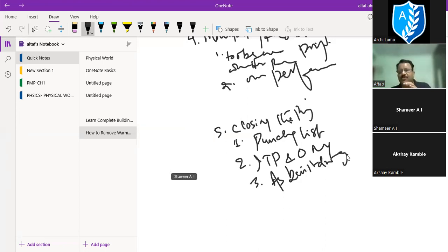What is an as-built drawing? Once the project is over, in the closing phase, from start-up to closing phase, maybe there are some changes in the project. Some part, definitely, there will be changes. Lots of changes are there in projects. Those changes are certified by the client or client engineer at those times, and they are checked along with the real measurement of the facility, housing or petrol pump or whatever we have constructed or developed.